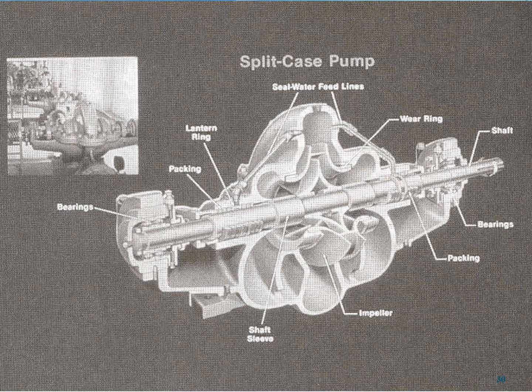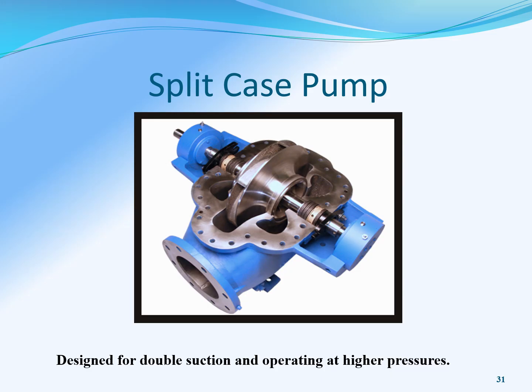This is a schematic or an open cut of a split case pump, which would be the mixed flow design that we had talked about earlier. As you can see, this is a super large pump. It can pump a large volume of water, but it also takes up a large space. So split case pumps are designed for double suction and they operate at much higher pressures. So like if you go inside some of the county water authorities or some of the larger distribution systems, this might be the type of pump that you see operating there.